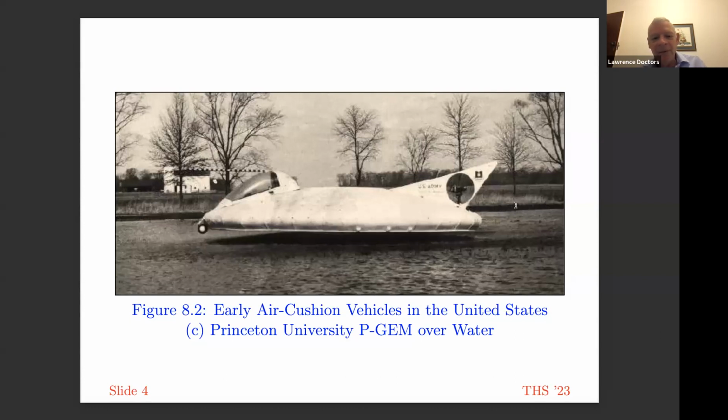The first is that you reduce the spray considerably, which of course is a big nuisance with air cushion vehicles. But a second interesting point, which I suspect a lot of non-technical people may not understand, is that if you do have a very large daylight clearance, as in this slide here, you have a very high momentum drag. So the drag on an air cushion vehicle is not only the obvious aerodynamic drag, but one also has wave resistance drag when traveling over water. One generates a system of waves, which increases the drag.